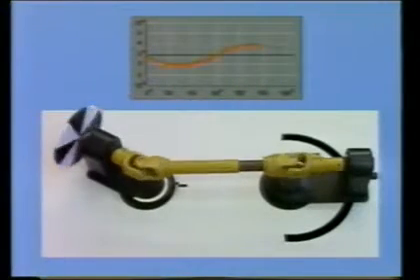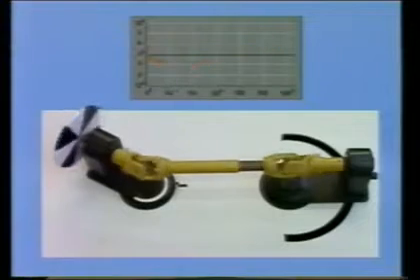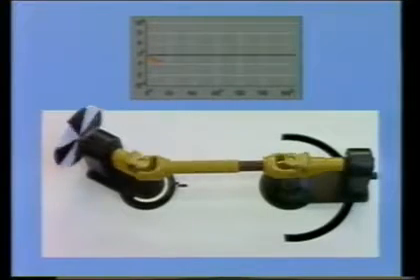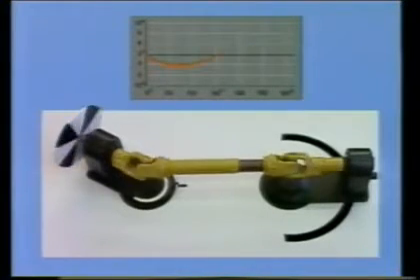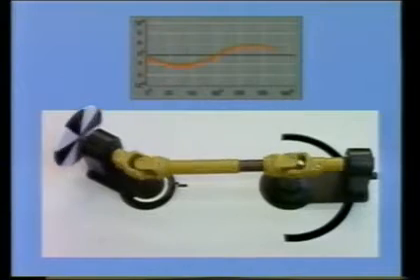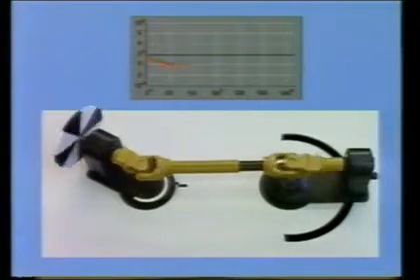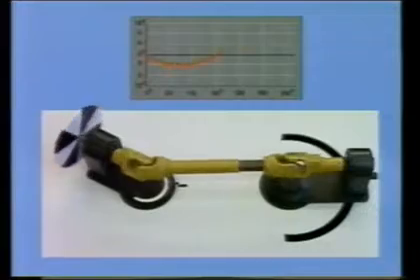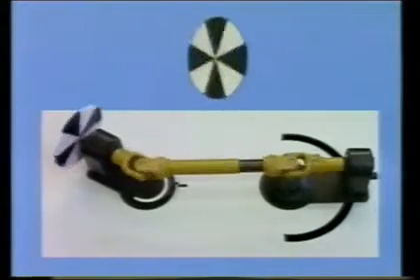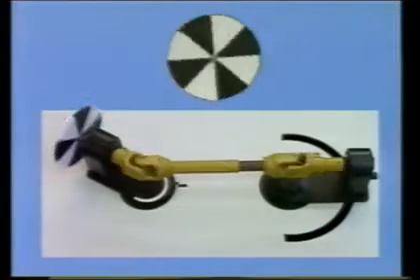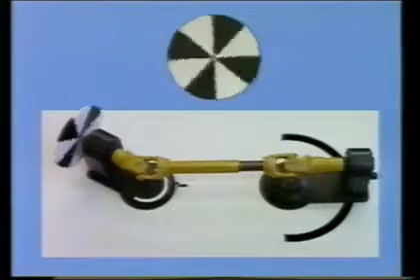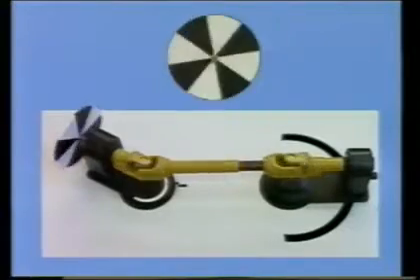At a working angle of 45 degrees, the velocity variation increases to 70%. The pronounced oscillations of the lead and lag angles can be seen in the graph. The black and white disc rotates extremely unevenly. The destruction of drive elements is the aftermath.